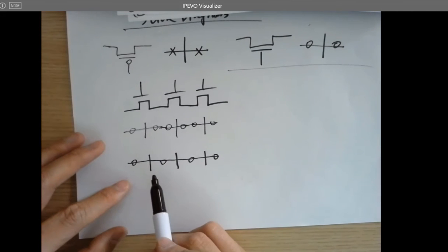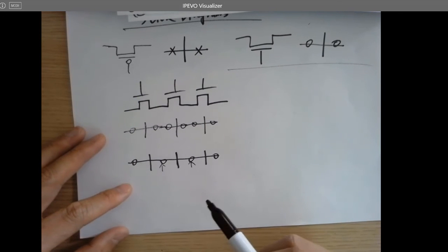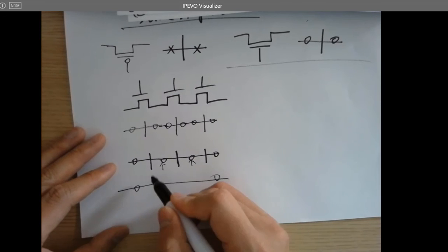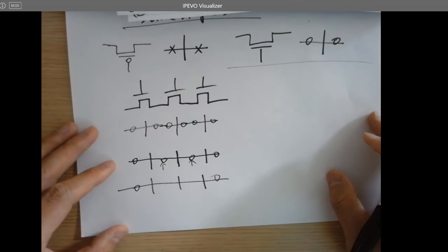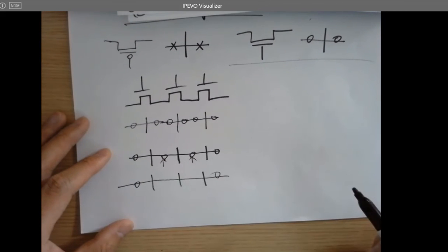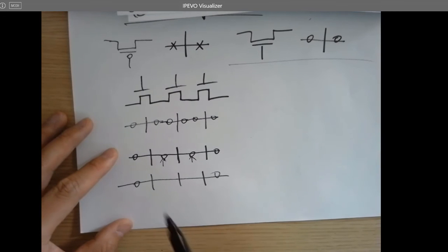Can this be simplified even further if you're not using these terminals at all? So the answer is yes, you can directly do this. Boom, boom, boom. Because this is just a metal node. It's nothing else, it's just a metal. So when you are designing the layout in Electric VLSI, you can also do the same thing.